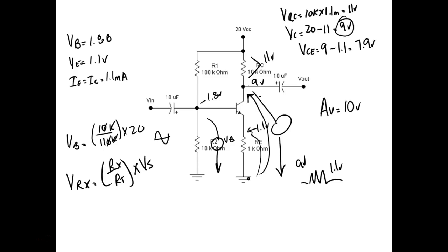So all it takes is you got your 2 meter leads down there, and you're looking over on your meter right there, and all it takes is just a little slip of your hand, right? You understand? And what did you do? You either shorted that thing emitter to base, or you shorted it base to collector. So you're shorting out 2 leads of the transistor, right? Which is going to cause, anytime we have a short, it could cause problems, right? You understand? I'm not saying it is, but it could cause problems.